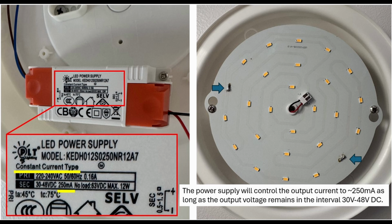In this setup, I had a 250 milliamp constant current type power supply that can deliver 250 milliamp at a voltage between 30 and 48 volts. But when I checked the power supply, I saw that it was good. So I did an ABA test where I swapped out the LED, since I had an identical light that I could swap the LED strip, the LED plate. And what I found out was that the power supply was good.